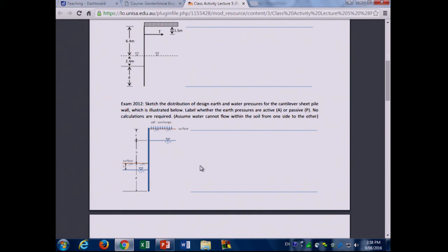I have a question here. You mixed up the water table on the left hand side. Yeah, the slope will change in the vertical stress diagram. This one you were given the effective unit weight. I said this one is wrong. But if this was given as effective, does the slope change here? No, then it doesn't change. It will follow that 20. I'd probably let it go, but I found only one student got it correct over there.